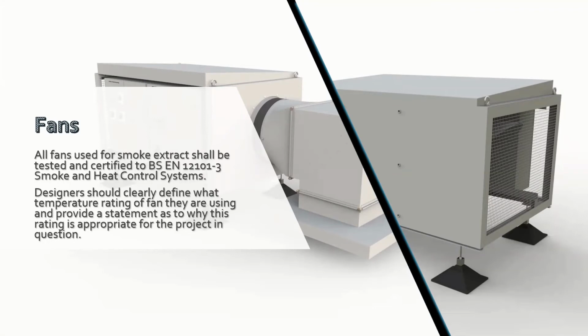They are independently tested at this temperature with a 1 hour run up, a 2 hour HT test and a 1 hour run down process before an independent certificate of performance is issued by a typical test house such as BSRIA. Standard ambient temperature fans should never be fitted for smoke removal due to the hot temperatures of smoke in a fire. Regular service and maintenance should be carried out in line with the fan manufacturer's guidelines and service procedure.